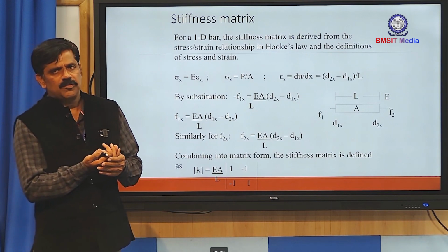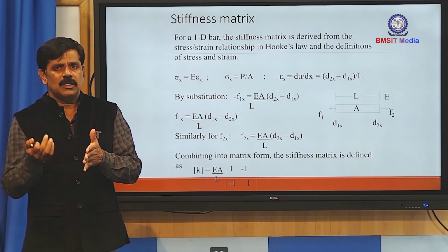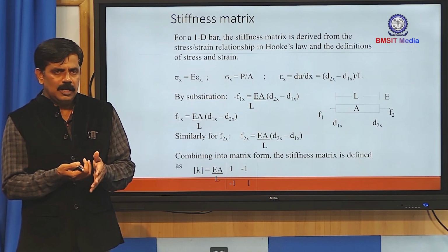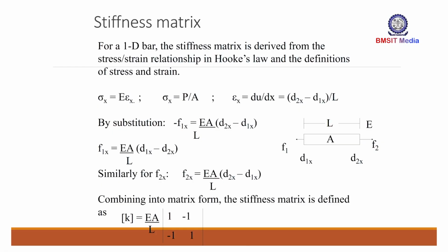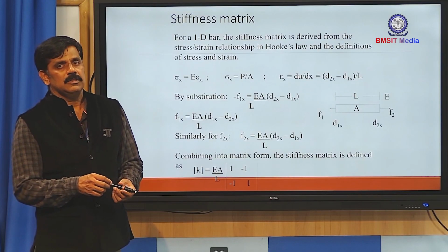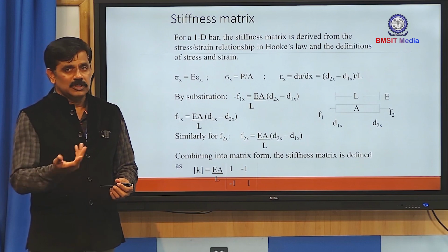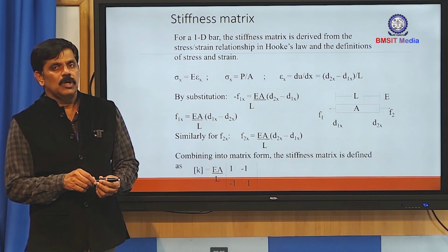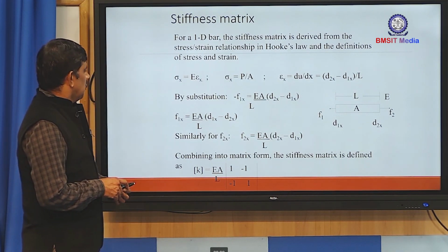and sigma x refers to the stress along the x direction. Once we have the strain and the Young's modulus, we can get the stresses, and that is nothing but the induced stress in the material. Once the induced stress is calculated, we can compare it with the design stress or allowable stress, normally the yield strength divided by the factor of safety. In most normal components, the factor of safety is taken as around 2. So then, from that we can get all the deformation.